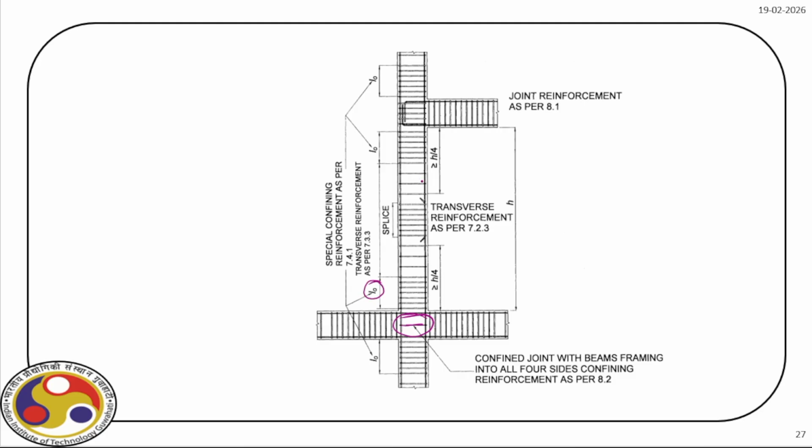Right? Then we have two different types of beam column joints. Here the column has a beam which is spanning on either side. However, here we have a beam which is ending on this column. So the rebars, as you can see, go here. Again, we have to ensure this development length plus these additional links here, along with the special reinforcement for